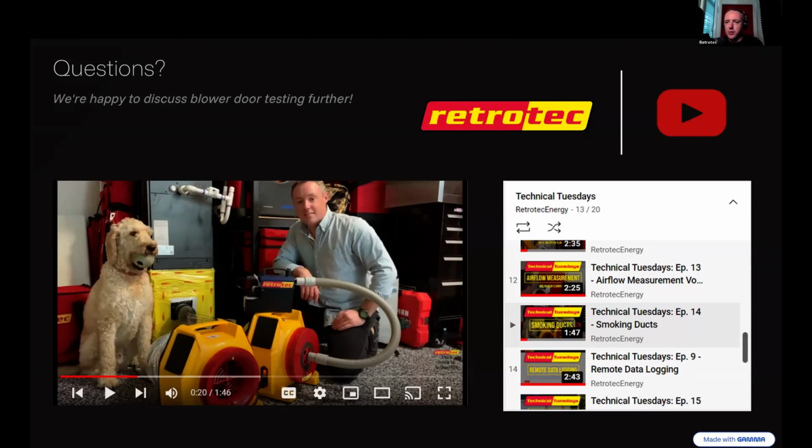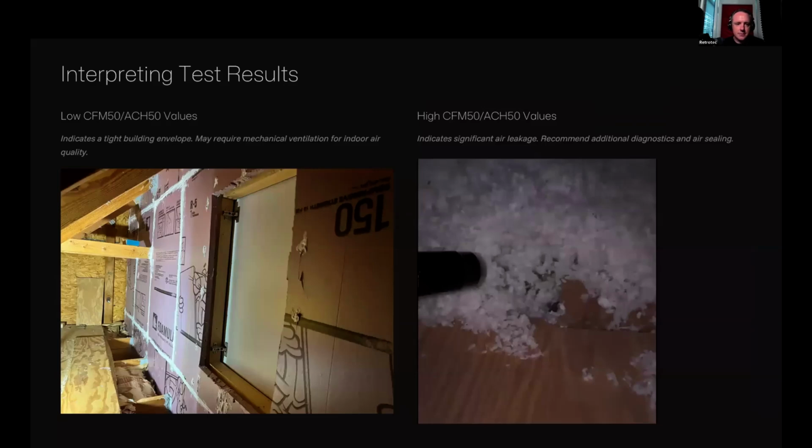And yeah, Noah, do we have any more questions? Yeah, I think I've answered most of them, but the one, if you go back one slide, it actually ties into this slide very well. If you ever notice that your volume number was incorrect, basically the comment was that ACH adds a step that you could forget or have some error. So it's always a good call to take a picture of the CFM as well. But so if you're getting a high or a low CFM or ACH 50, it is always a good step to double check that your range settings are correct and everything as well.